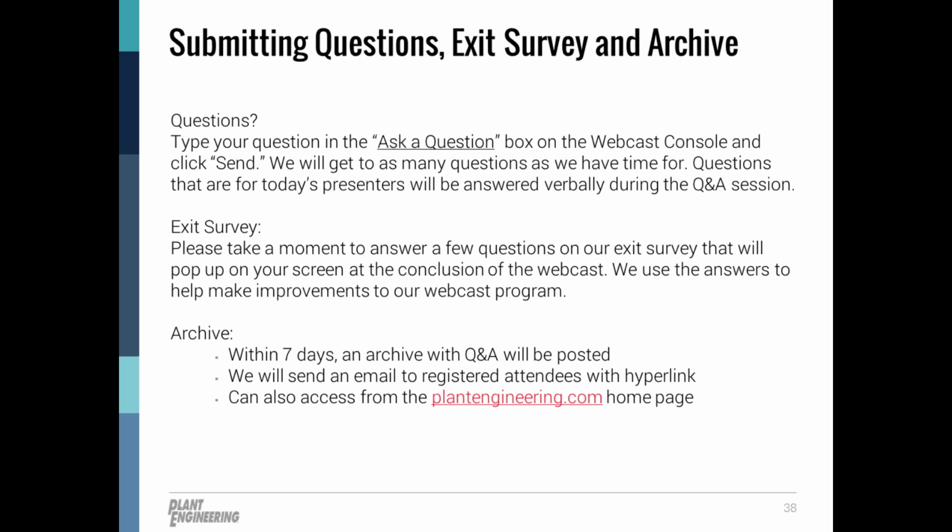Yeah, I could start on that one. I think you will be listening for audible noise. If there is a misalignment, you hear some audible noise. You can use the vibration analyzer if you have one to verify that. I'm not really sure on a larger issue with vertical versus horizontal. Okay. Well, thanks for taking it. Ronnie, did you want to take a swipe at that one?